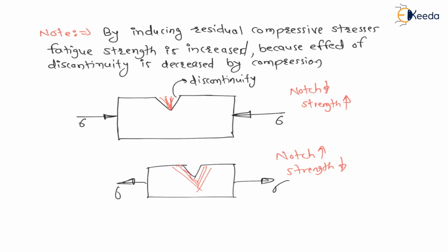Means if I apply residual compression, means initial compression before loading, initially we are compressing the component so that the fatigue strength is going to increase.